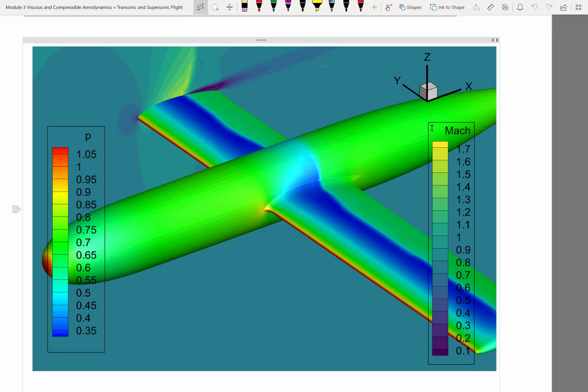What is happening is that as the flow goes supersonic, if you look at the contours of the Mach number, it keeps increasing velocity. That means the stream tube area, as I move from here to here, actually would increase. Unlike a subsonic flow case, where the suction peaks here and the velocity also peaks here, the streamline contracts and expands.